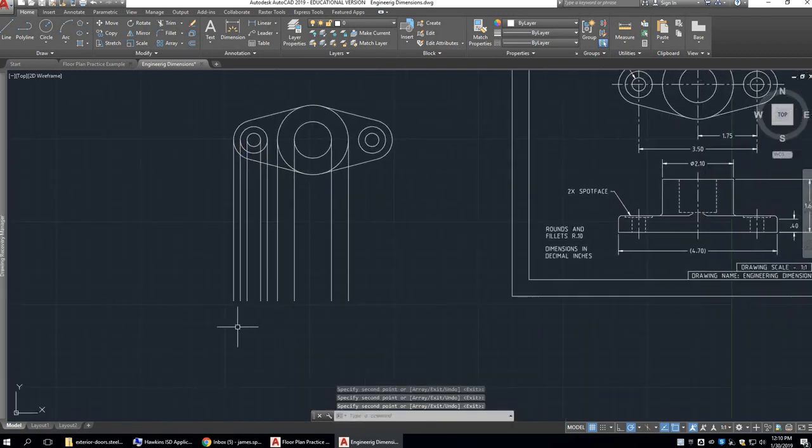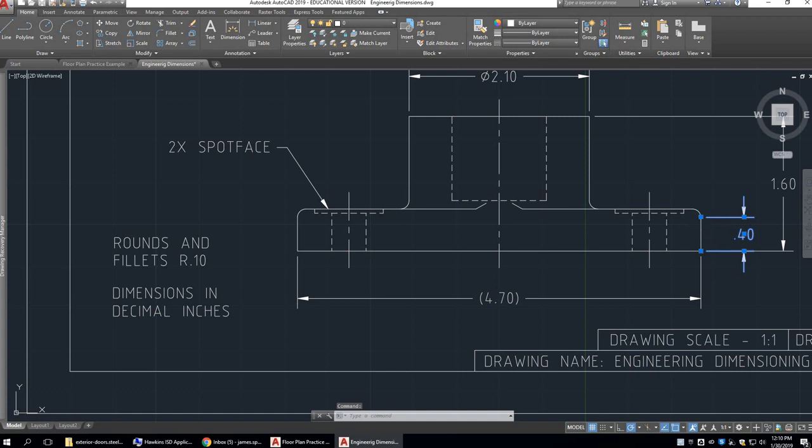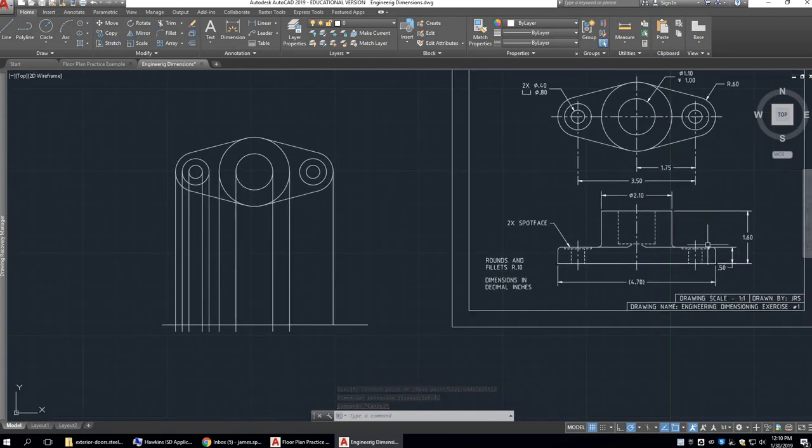Alright. And then I'm going to draw another line, L, enter. I'm going to come just right up here so that this will cross my other lines, and click, and I'm going to draw one more line from that midpoint or quadrant straight down to where it hits that line. So that is the overall size of my object from there to there. So this object is 0.4. No, it's not. It's 0.5. That dimension was a little off there. So it's 0.5 from the bottom up.